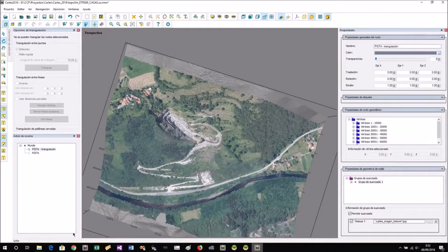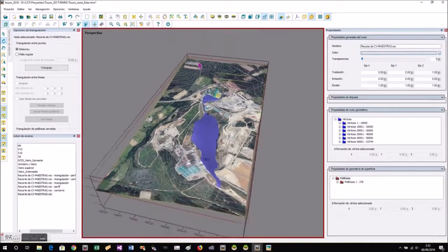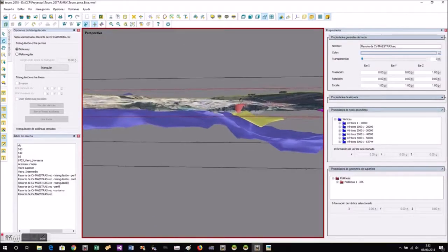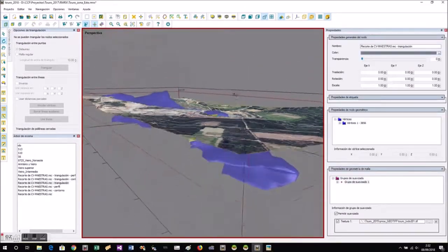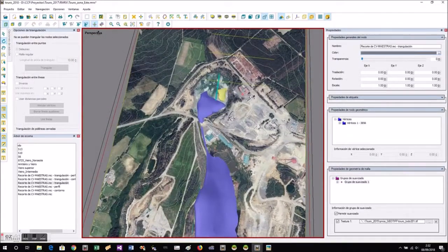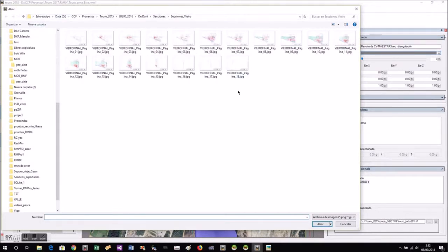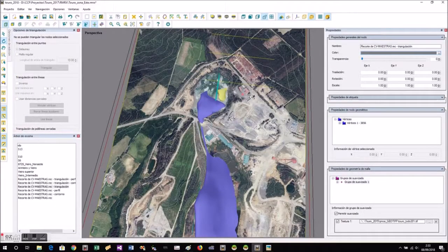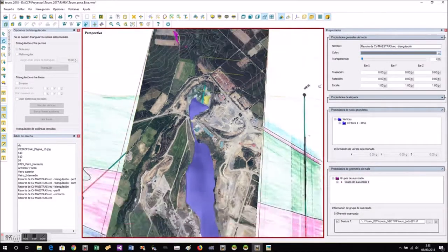Right, when we georeference we have the options to tell it whether it is parallel to the XY plane, or parallel to the ZY plane, or parallel to the ZX plane, the 3 main planes. We can also tell it that it is vertical. Many sections are vertical. Or oblique, I mean not vertical. Parallel to one of the main planes, and also that it be free, that is, it can be anywhere in the space. In the latter case it's when we will have to give it 3 points. With 3 points we are giving it a plane and we are saying where in the space it is.